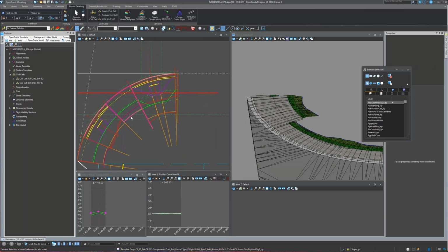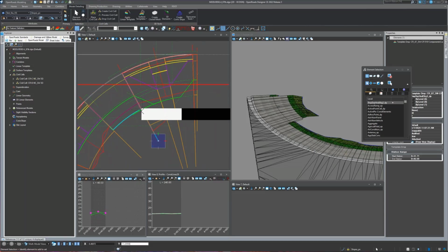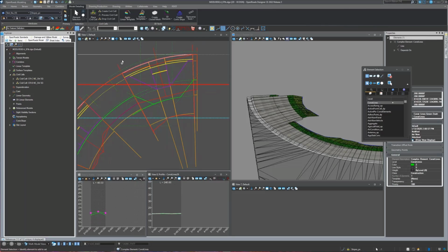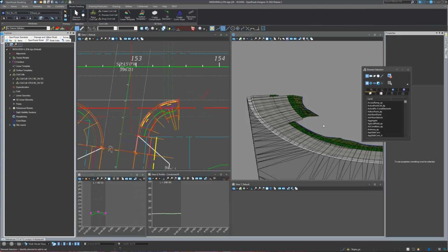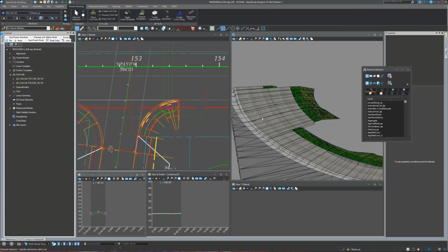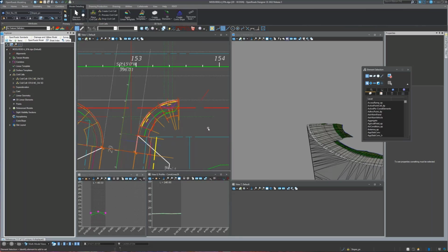Again, I would want to button up these to snap to here again so that if anything adjusts, it all moves together. But that's pretty much it. Sorry that one didn't work for some reason. I'll have to check into that. It's definitely something to do with that horizontal feature constraint and it looking in the wrong direction for my external references.